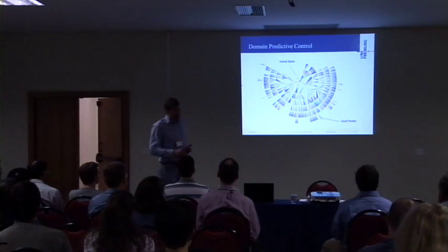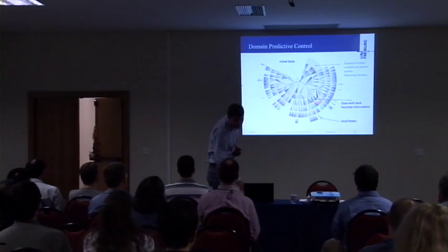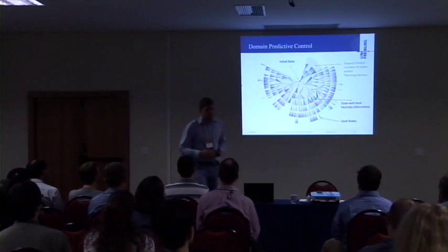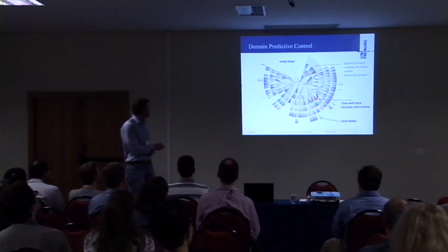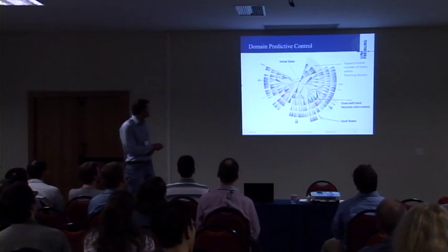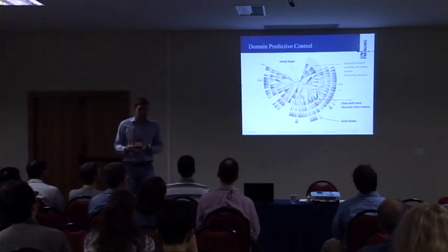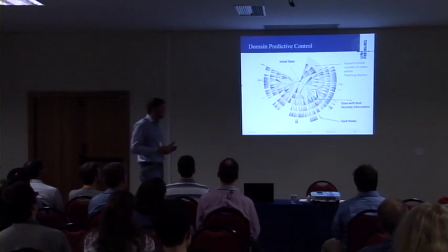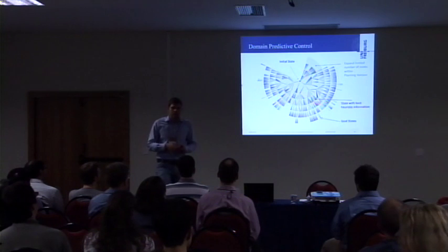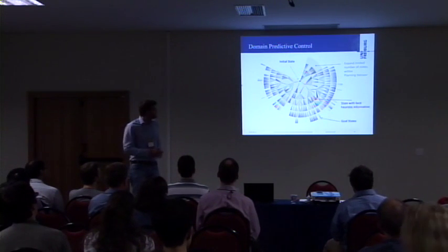That's why we use a prediction horizon. So we only plan to a certain depth of the decision tree, for instance, here 4 steps. Additionally, we limit the number of states to be explored by the planning algorithm. The planner will then return a state which is good regarding heuristic information.